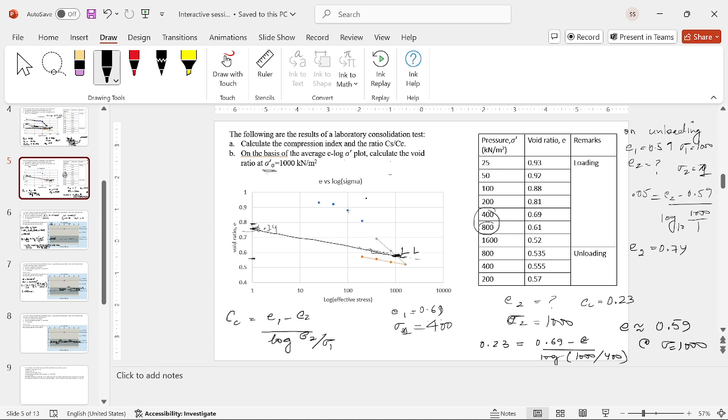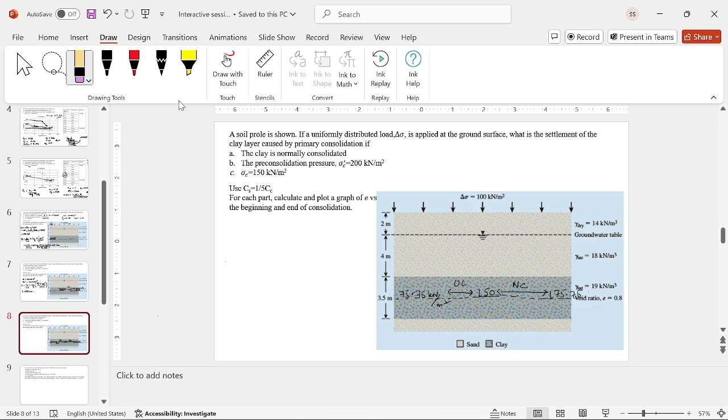So if we go back here, if 150 is here, the soil loading will start at about 75. It will behave as OC soil with Cs slope, and as soon as it reaches 150, it crosses over and becomes NC soil. Okay, for this we have to split the term for the calculation of settlement into two parts, the OC part and the NC part.